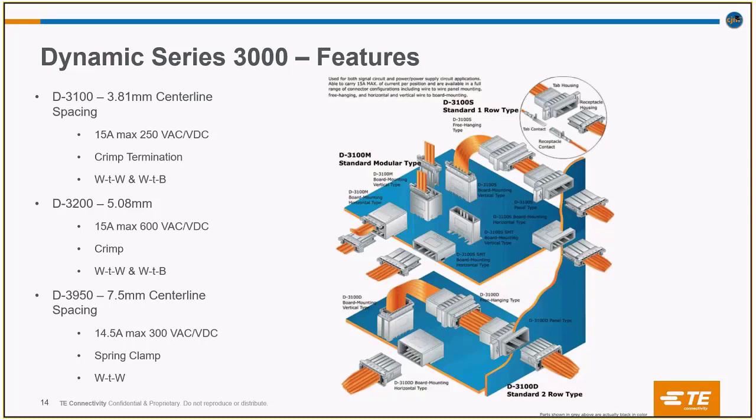There are 3 plating types. One is tin, the other 2 are gold, but it depends on the plating thickness as well. In a normal environment, tin plating can be used. Where there are a large number of insertions, gold plating of 0.38 micron thickness is used, and where the environment is much harsher, again a thicker gold plating is used. So there are 3 types of plating: normal tin and 2 gold platings with different thickness.